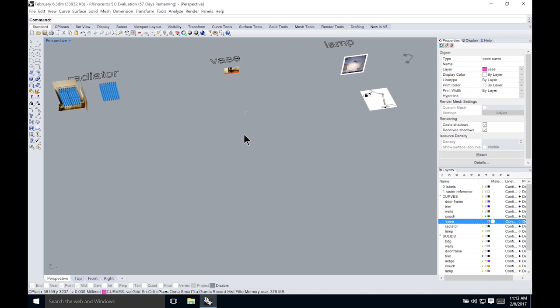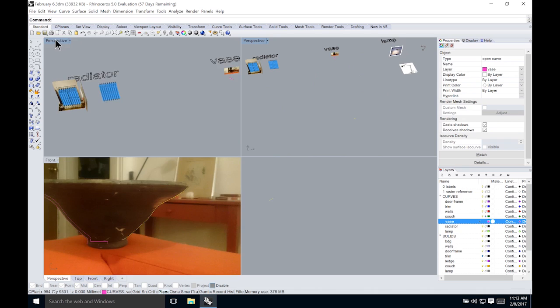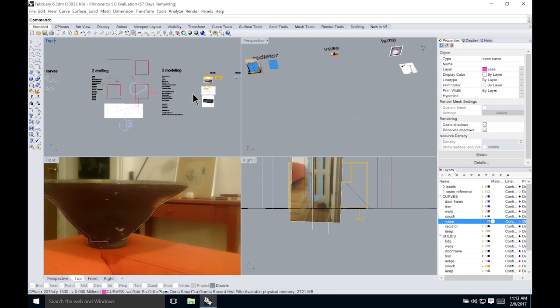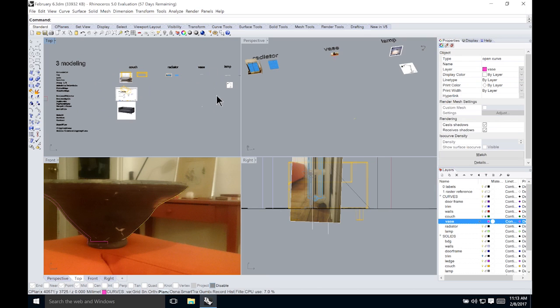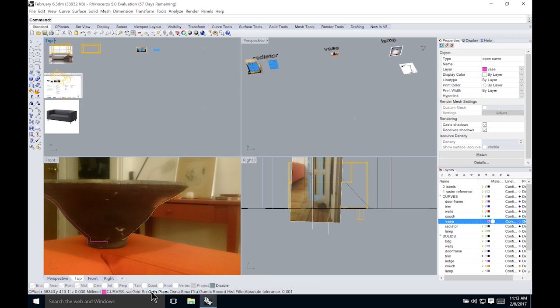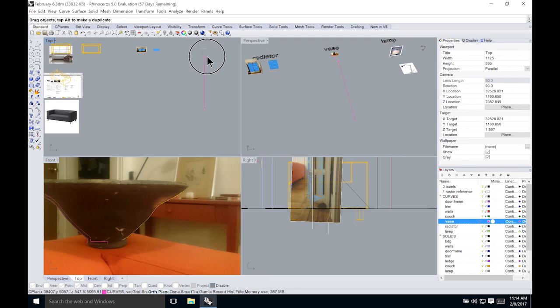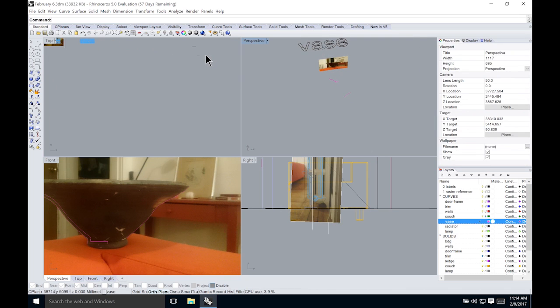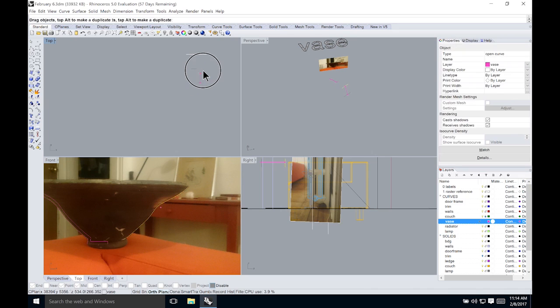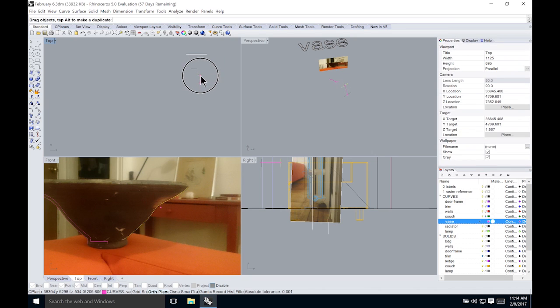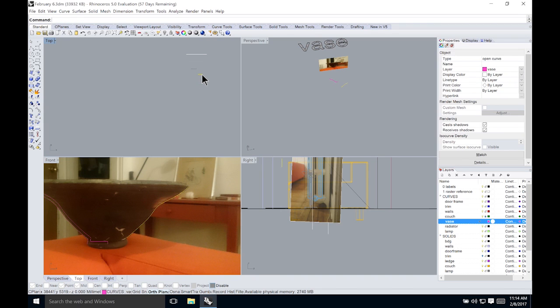And actually before doing that, that's probably better to do in top view. Yeah, so here's my curve, and for that I'm going to definitely turn ortho back on, so that I don't mess up the orientation. So you can see in the front view I'm moving this from front backwards, but in my front view it doesn't change at all, because those coordinates are preserved.